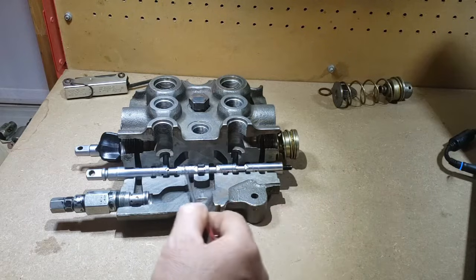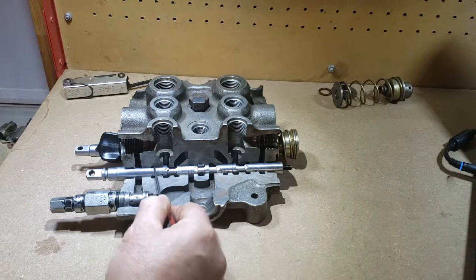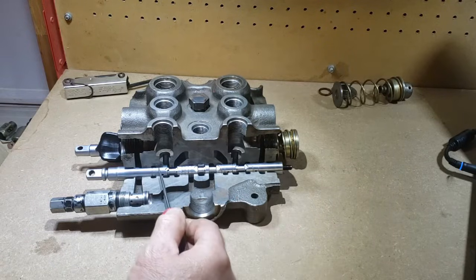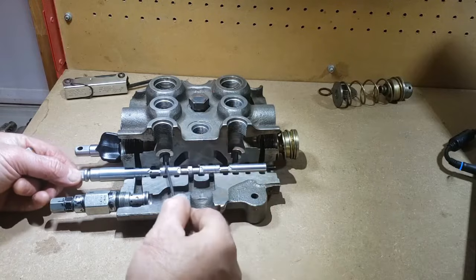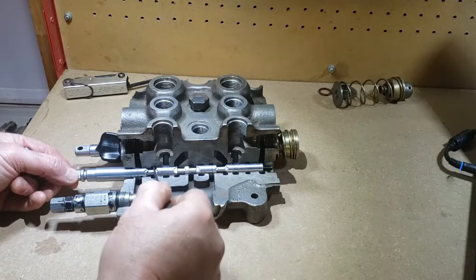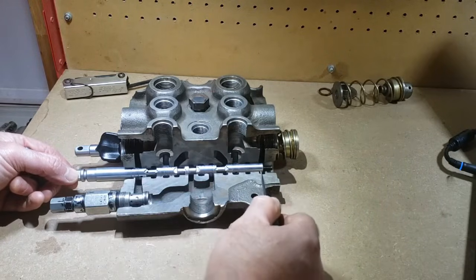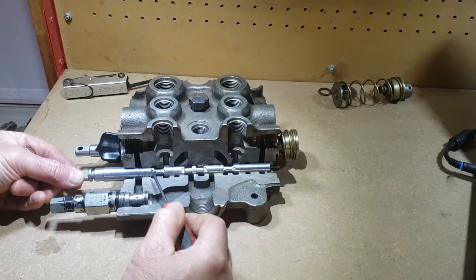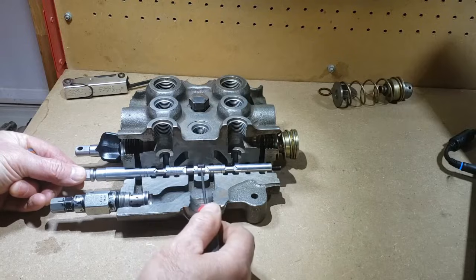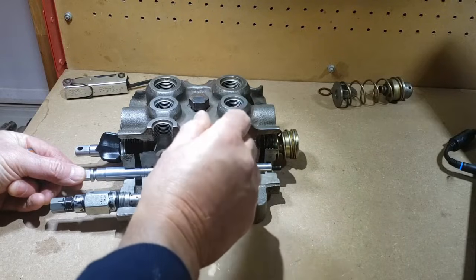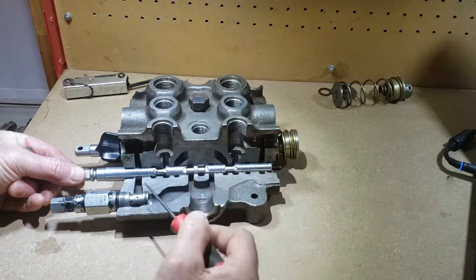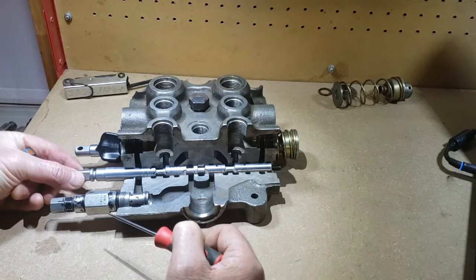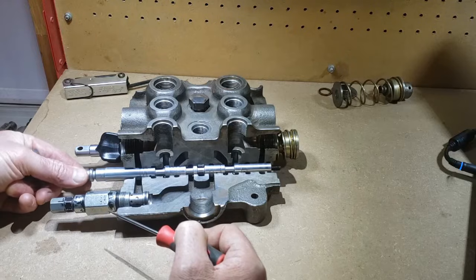Now, I've been mentioning that these return ports are going back to tank. That's not entirely true. In either case, when oil's returning and going into these passages, the reason it doesn't just dump into these passages out here that literally go back to the return is because this is a valve that actually feeds the returning oil from the lift back into the open center path downstream of lift, so it can then feed tilt. So this is again a modified series valve.